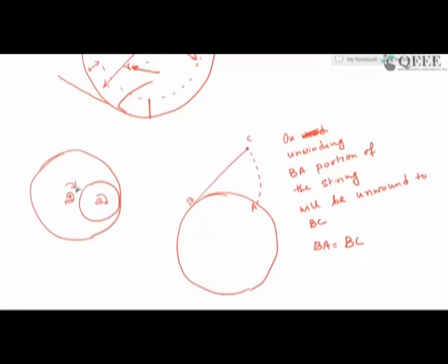The law of gearing remains the same: if this is capital R and capital omega, and this is small omega and small r, you still have omega r equals capital omega R. Internal gearing will be very common in planetary gear systems, which is what we will talk about. So when we analyze internal gearing, we will take the same formula, except that we will not care for the sign change, because both the gears in an internal gearing arrangement will have the same sense of angular velocity. Just a few more things before we leave the simple gear train.